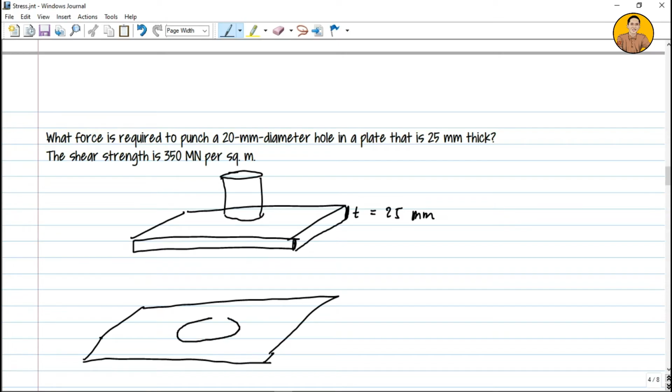So there is a hole there. We see we have this, so our plate has been punched through. If this is our force here, as you can see in the figure, if you punch it here and it gets perforated, the area under stress is actually applied on the sides, the parallel area. If you imagine that, it is the punched area on the side, so the area is actually parallel to the force. This is a shear stress.